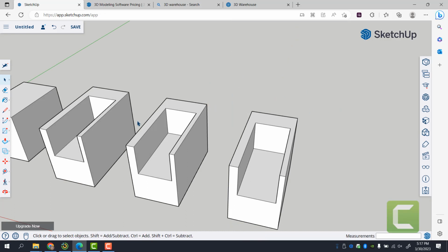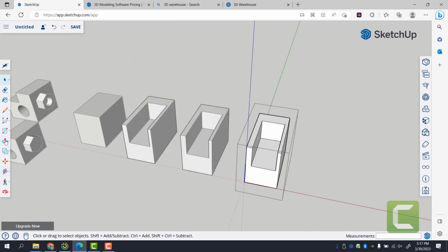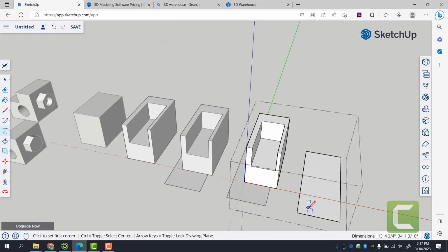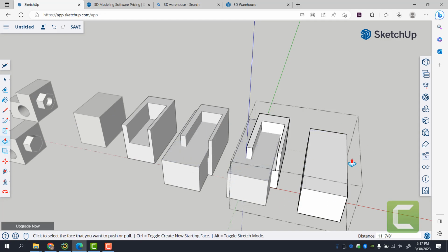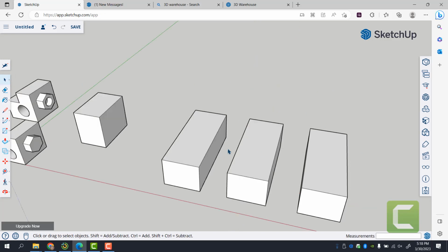How I would utilize this feature is I would model one chair and place it in the entire theater or the entire school. If the client decides to change the chair or a different model has to be substituted, I can simply go in and alter the component itself. And once I alter this component, and let's say I brought this box in, I can simply say, okay, goodbye old chair. We're going to get rid of that, and this is going to be the new chair. And simply put, if you use the same origin, it will replace the object altogether.